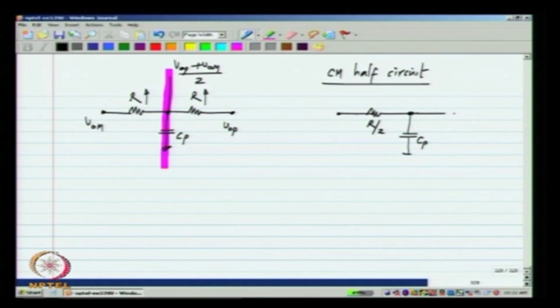So, here I have the common mode output and here I have the detected common mode, and it is clear that for higher frequencies the detected common mode is not the same as this, because this is a low pass filter. Now, this can also be a problem.